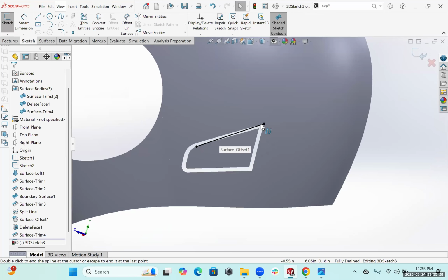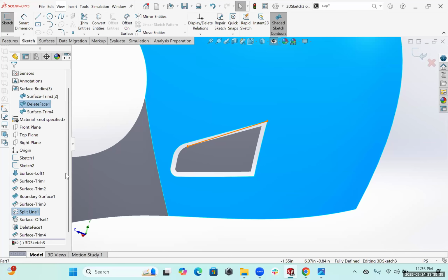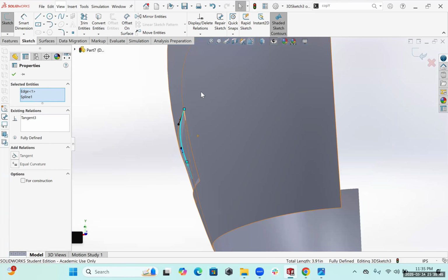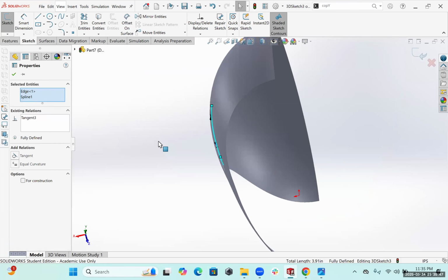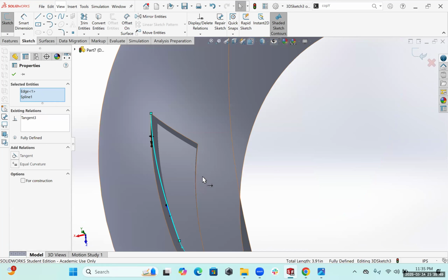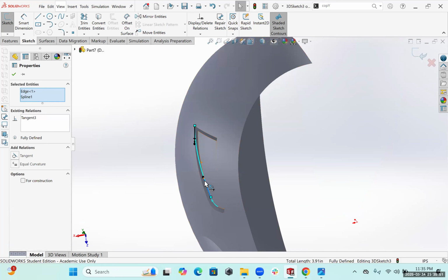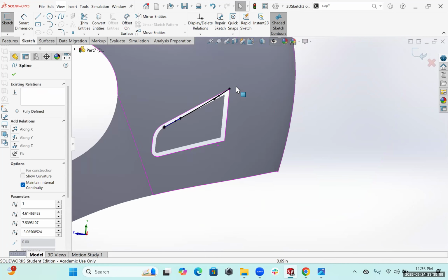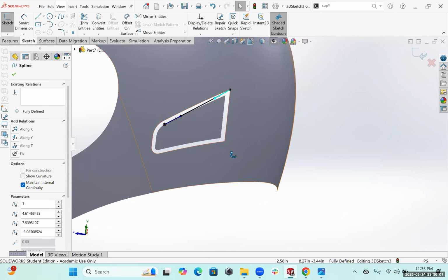Now I have to set this and this to be tangent, and this curve and this to also be tangent. Also gonna look here, make sure. So the surface is gonna come in. So I need this to be smoother. That one doesn't matter as much. So I'm gonna push this out if I can more. So there's a nice smooth surface in here.